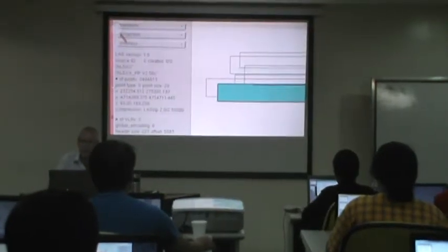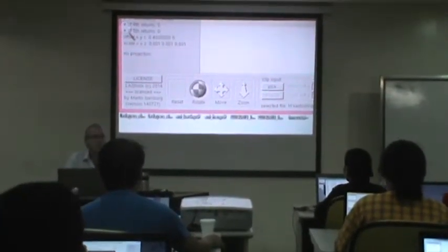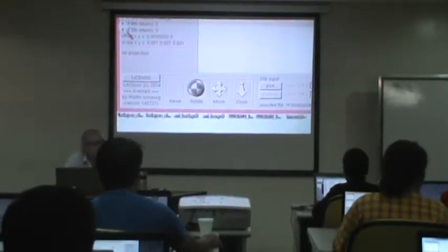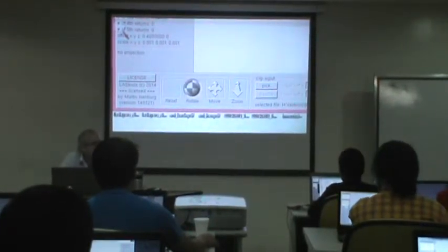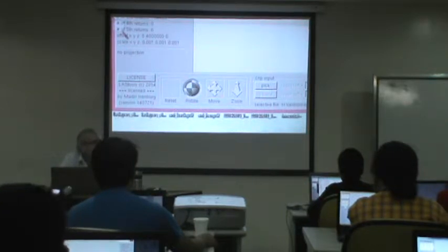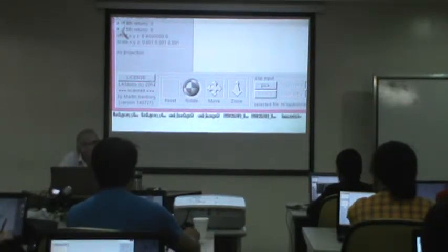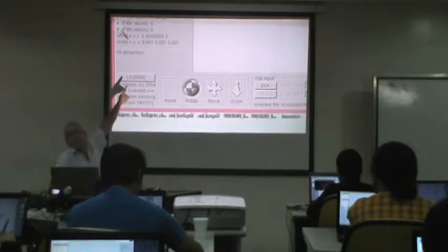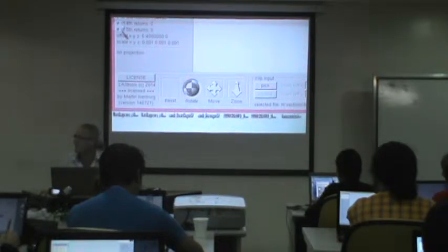It is important, however, if you want to use KML as an output, that you need to know the projection information, meaning you need to know where the LiDAR data is on the globe. And these particular LAS files don't have projection information. That often happens, that you get LAS files and they do not have projection information.